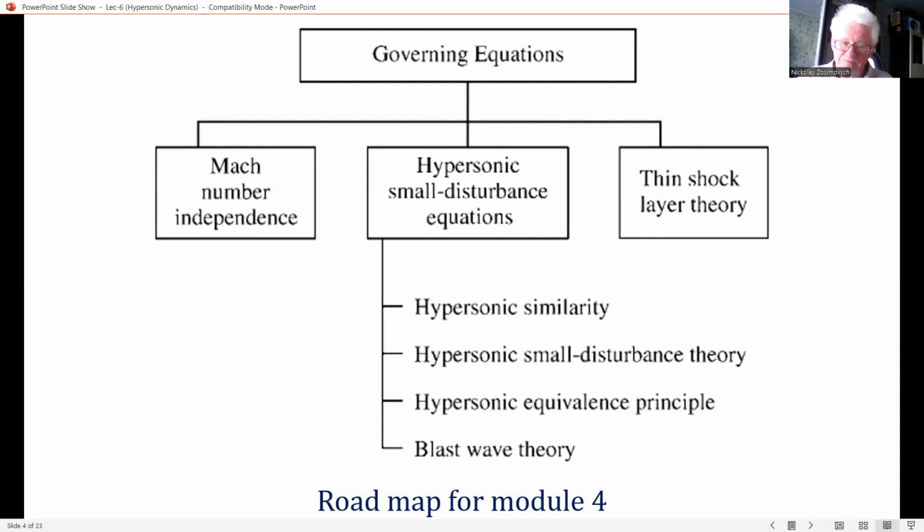on this slide. It is important to know that in our discussion of both Mach number independence and hypersonic similarity, we have only examined the appropriate equation. We have not solved that. Hope you remember this. Specifically, our examination of a non-dimensional form of the Euler equations and the boundary conditions, the same on lecture 4, clearly demonstrated the mathematical justification for Mach number independence.